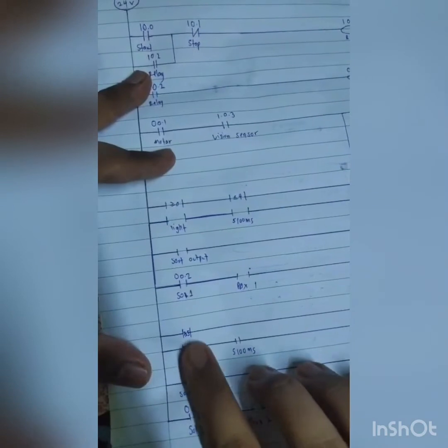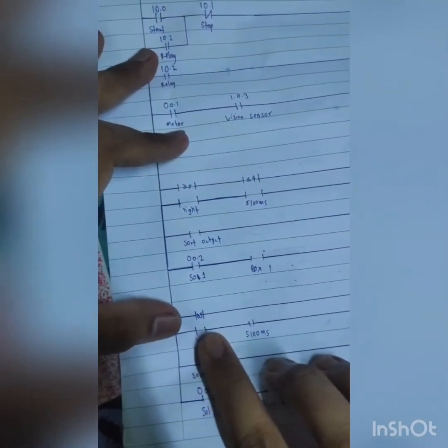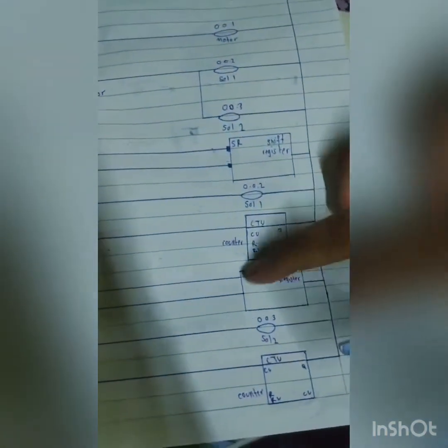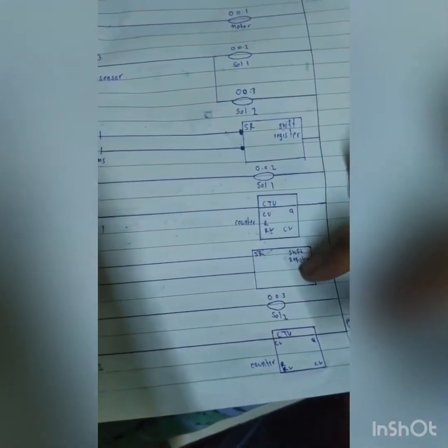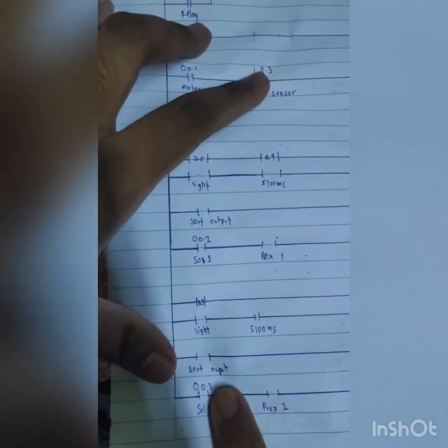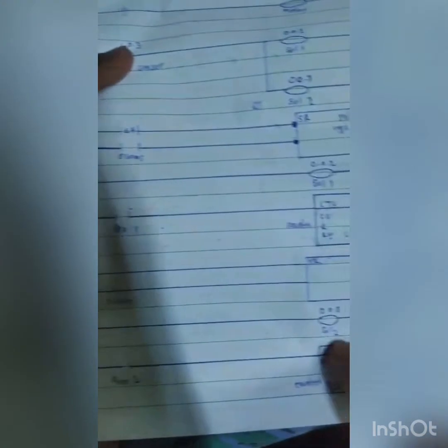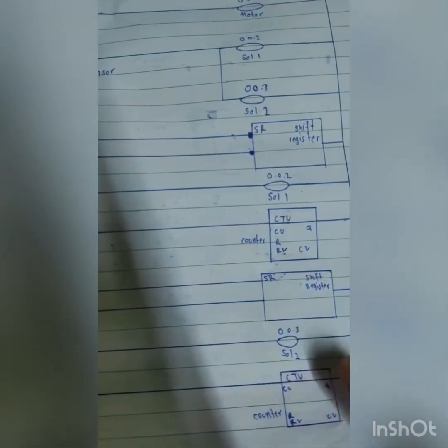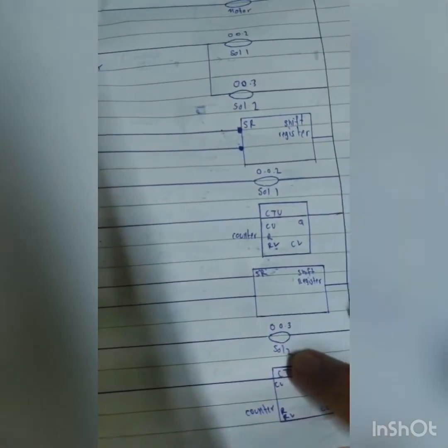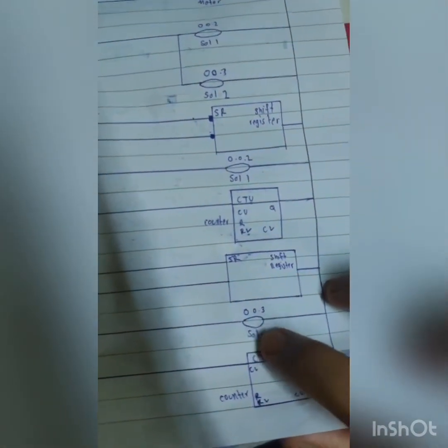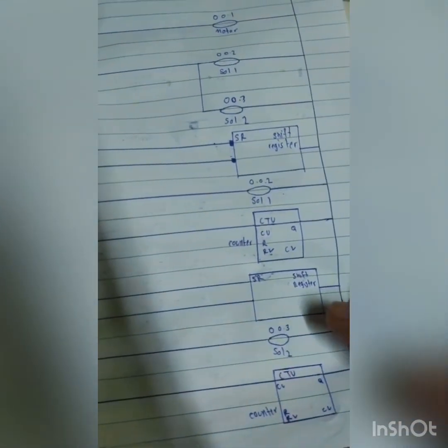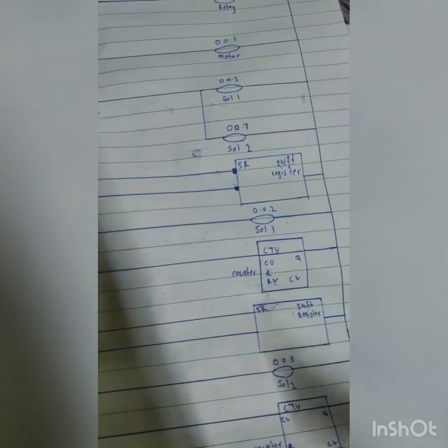When the blue part unit is detected, the vision sensor sets the SR, which means shift register, and the sort output will send information to the solenoid 2 to activate. That means actuator 2 will extend and push the parcel to exit 2.